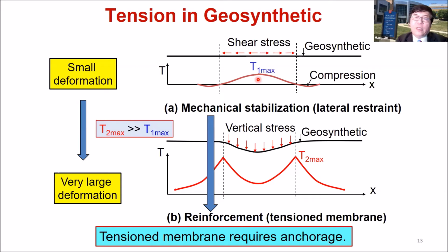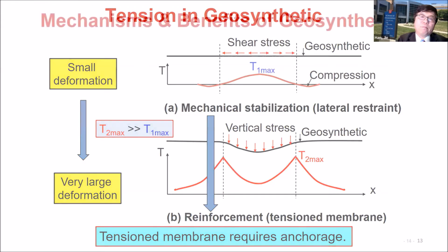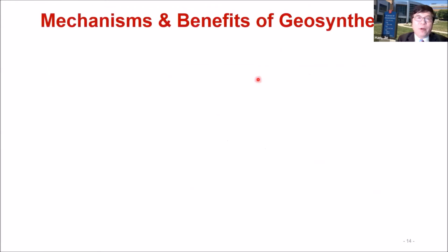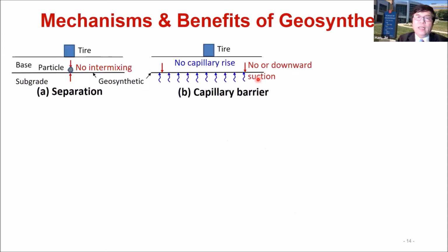The case that I mentioned at the very beginning, why the geotextile did not work to support that person, is because there was no anchorage on top of that geotextile. Okay. Now let me try to summarize the mechanism and the benefit of geosynthetic for roadway application.